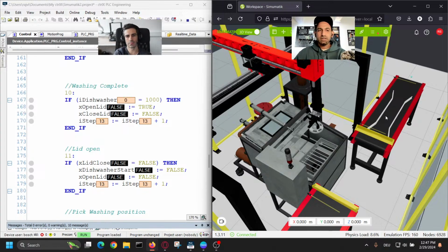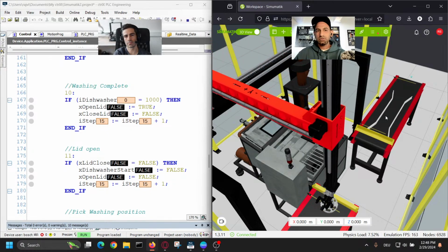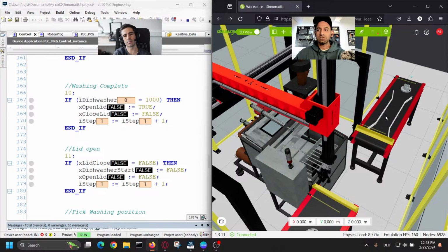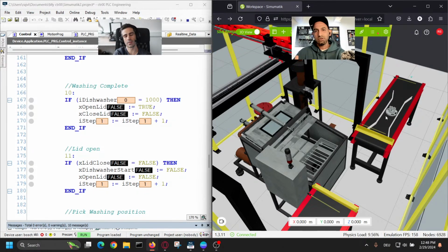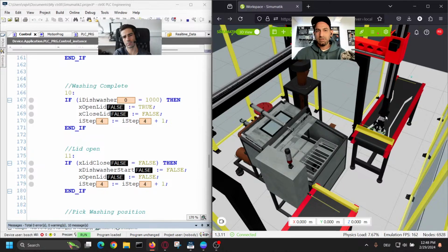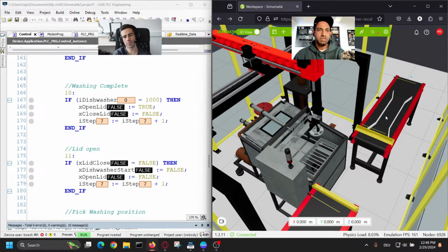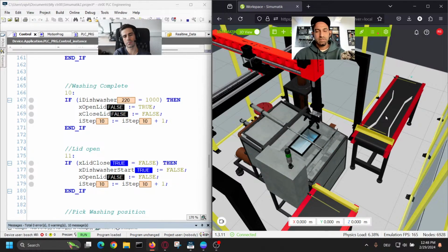And another important part is, when I share this project, this Code Assist project, if you don't have ctrlX Core, you can use ctrlX Core Virtual as well. So in this case, you don't need hardware. You have a soft PLC or soft ctrlX Core. You can still execute this program. And you can also execute the same code if you just connect with Code Assist. In Code Assist, you have soft motion possibility to have a virtual axis. And I think the programming would be the same. You just need to maybe change some axis names and how you declare the axis. And the rest, you can use the same sequence and play around with the system.